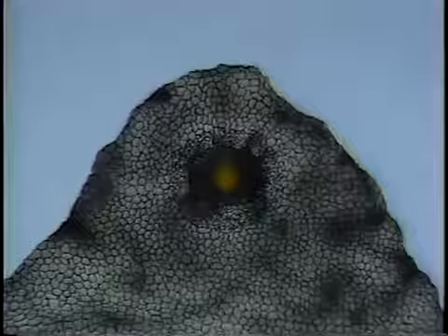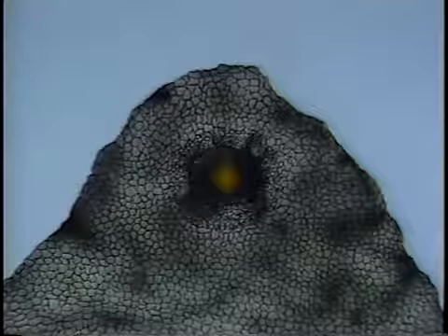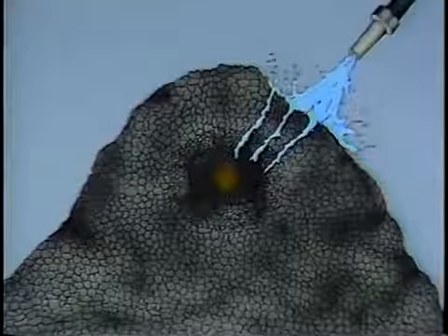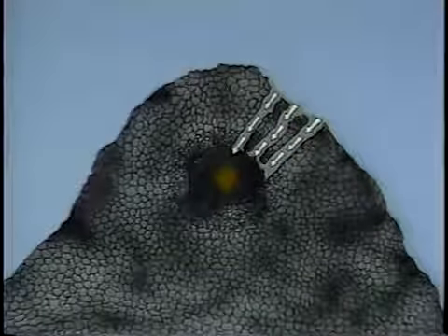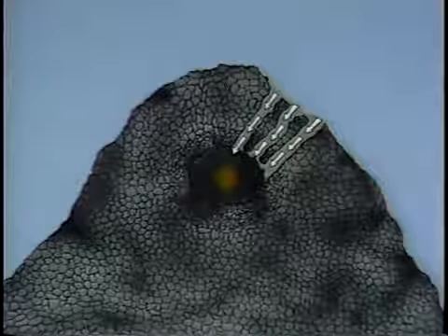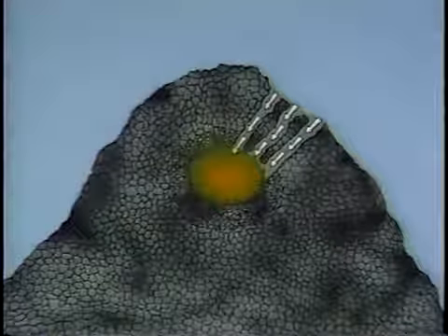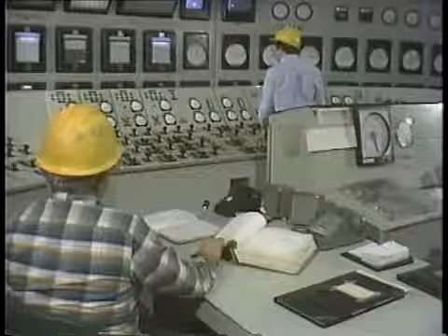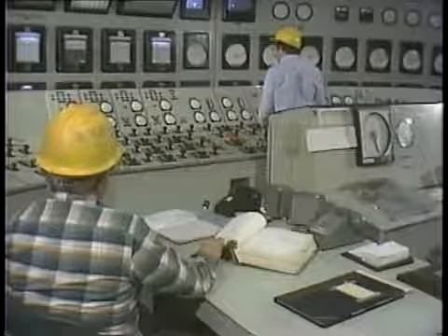In some cases, water can also make the fire worse. Fires in bunkers and coal piles generally occur deep down in the coal. Water has to filter through the chunks of coal to get to the fire. In doing so, the water can cut passageways for air that can actually feed the fire and increase combustion. In all cases, your plant will have specific procedures that you should follow when dealing with equipment fires.